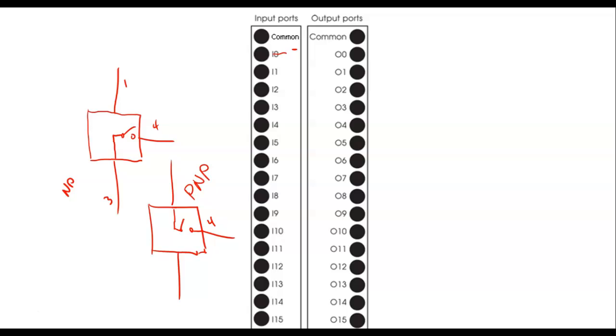And it's in the part number. If you just call the company that makes it and you say, I need an inductive sensor, and they say, well, you need a PNP or NPN, and you say, well, I guess I'll get an NPN. And then you hook it up and it don't work. And you pulled it out of the box, you paid $60 for it, and now the company won't take it back because you already mounted it.